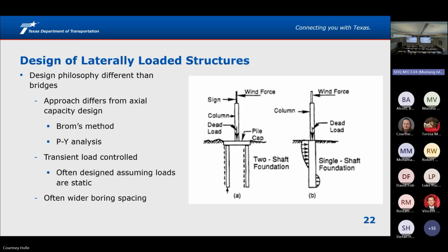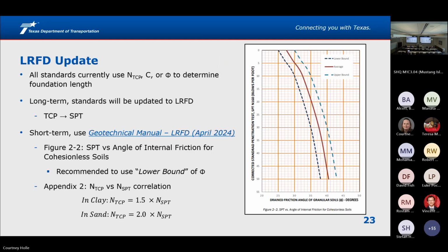Those are the kind of things that, when you're thinking about this from a geotechnical standpoint, you're trying to figure out exactly how variable the soil is and how much I can rely on it. Because if that information is relatively far away, then I might make a more conservative assumption based on that.